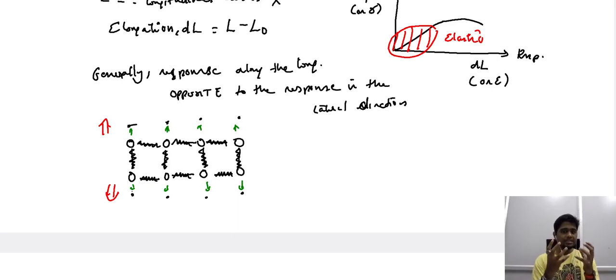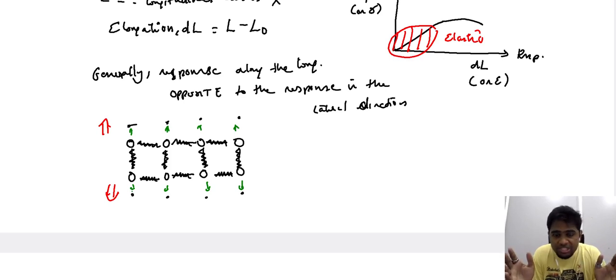So the reason behind this particular behavior, the change in the lateral dimension in addition to the longitudinal dimension when you impose a uni-axial tensile loading, stems from the continuum that is established between the atoms that comprise metals and alloys. In metals and alloys, you have a regular arrangement of the atoms, and this regular arrangement of the atoms establishes a continuum through these bonds. Through these spring-like bonds, they establish a continuum.